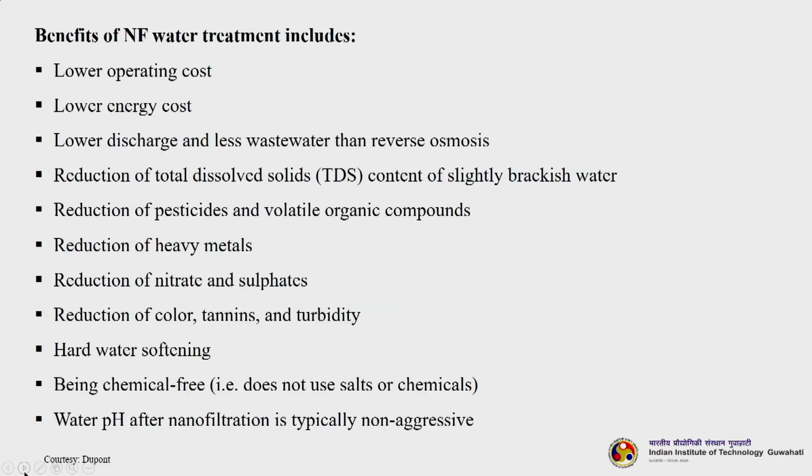Let us understand the benefits of the NF water treatment. Most of the time NF is actually used to produce potable water. So, in that case what are the advantages? The operating cost actually is very less, energy cost is also less, lower discharge and less wastewater than reverse osmosis. Then reduction of total dissolved solids content of slightly brackish water, reduction of pesticides and volatile organic compounds, reduction of heavy metals, reduction of nitrate and sulfates, reduction of color, tannins and turbidity, hard water softening, being chemical free. So, it does not use any salts or chemicals. Water pH after nanofiltration is typically non-aggressive.